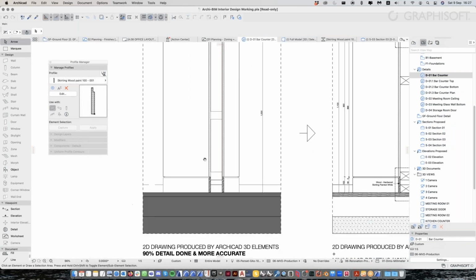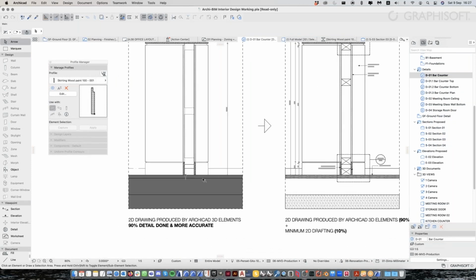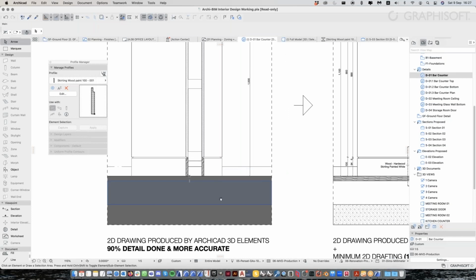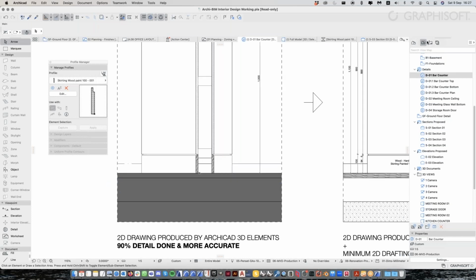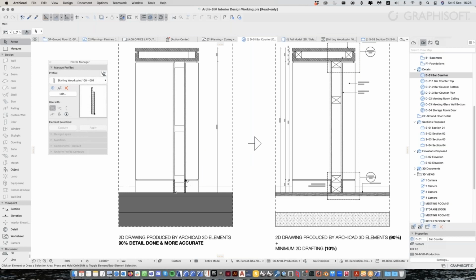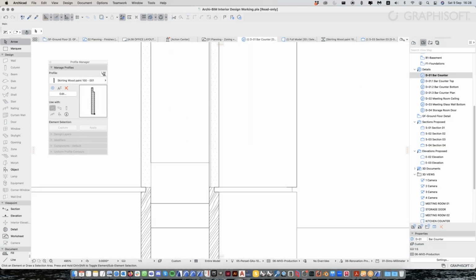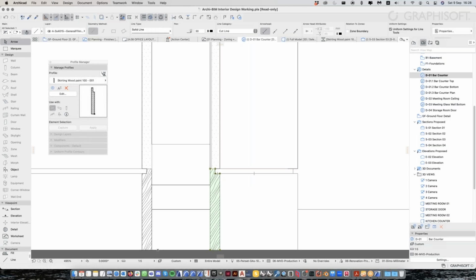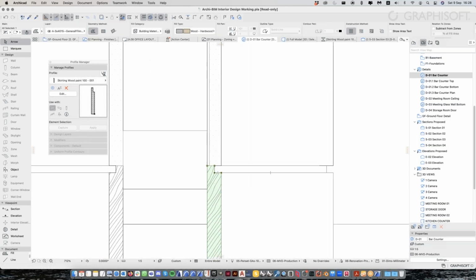So this is just a tip for using the marker tool. It doesn't reflect the change immediately because you will need to rebuild the drawing. And when you rebuild it, it will update to the latest state. But if you already started changing some of the fills, maybe adjusting things, then the change will revert.